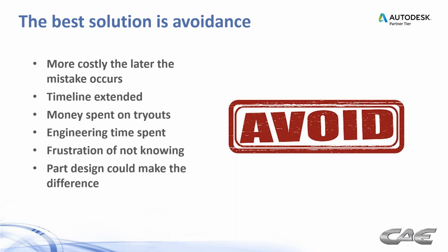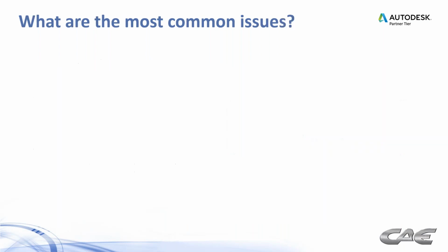And one of the big reasons behind that is that oftentimes it's a part design solution that can't be made once the mold's built. How many signatures does it take to go back and get a part design change approved once the mold's built and the production starts up? So we want to try to use Moldflow early on so that if the solution is a part design change, we can suggest that early enough where we can get that approved.